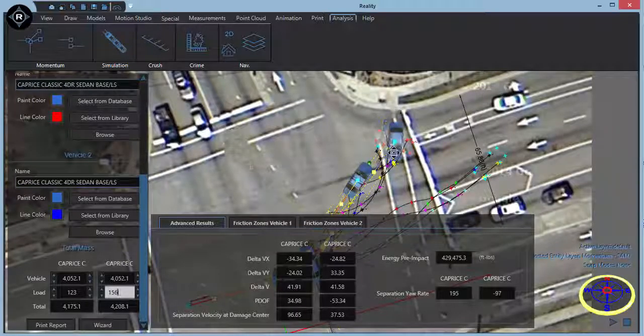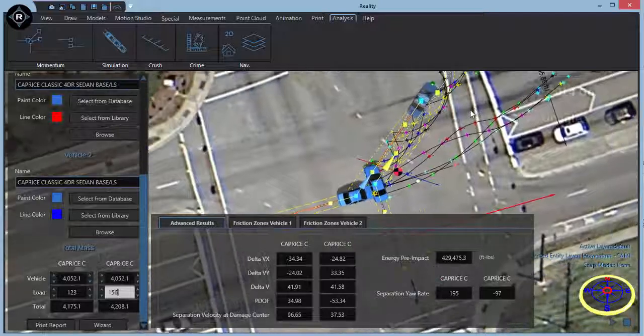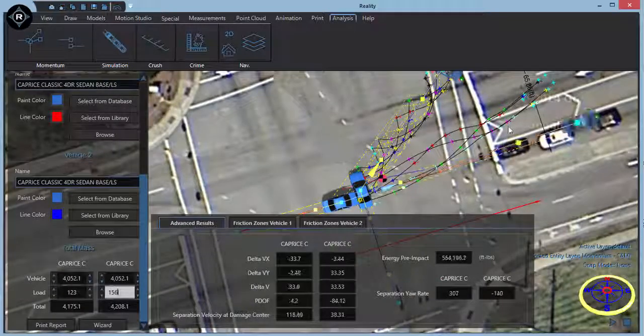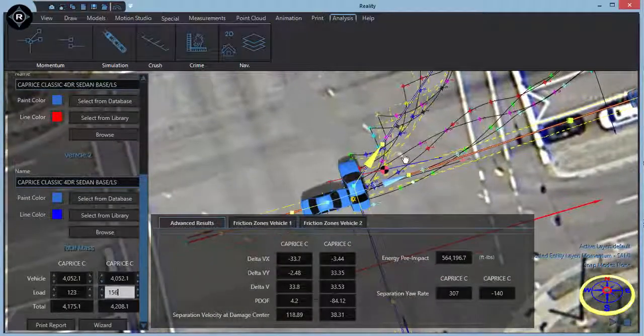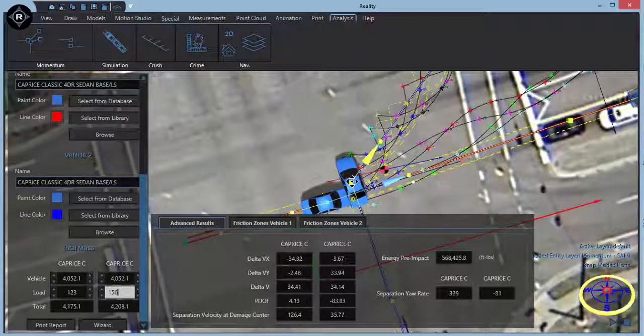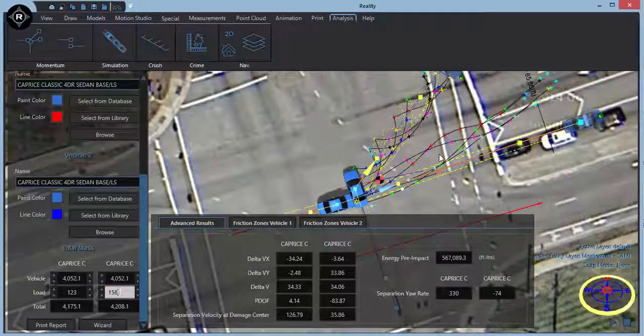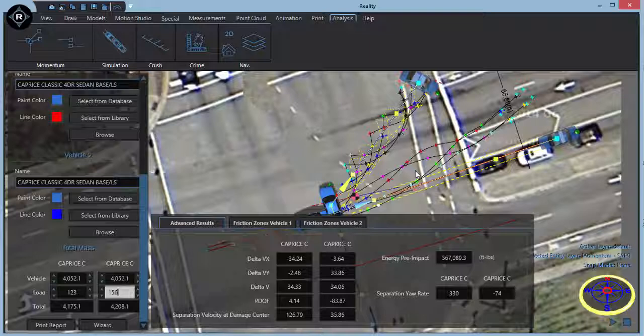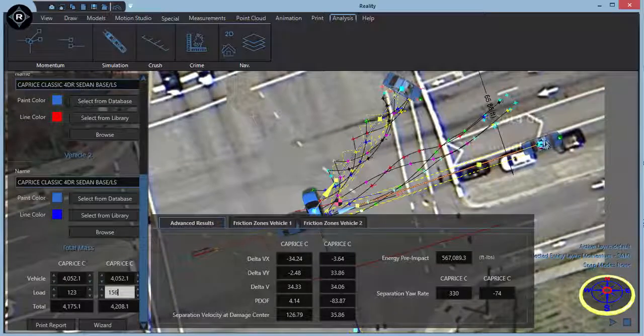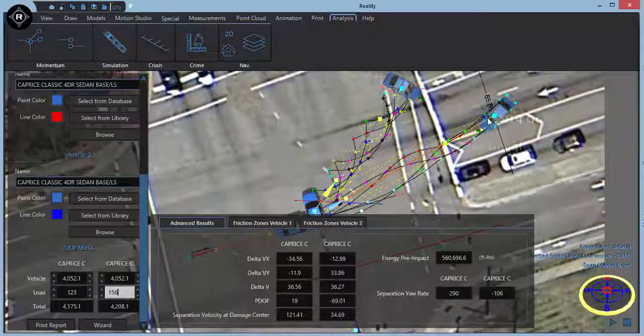It rotated twice, so we'll spin this vehicle twice and try to get an agreement between the simulated tire marks and the real ones. And that shows we really need to move this car a little further in that direction. And now we've got a pretty good agreement. We have to put in some interim positions to get it to actually follow the lines precisely, because there's been some uneven deceleration there. But for the first calculations, that's not a problem. And this vehicle did a 180 like that.